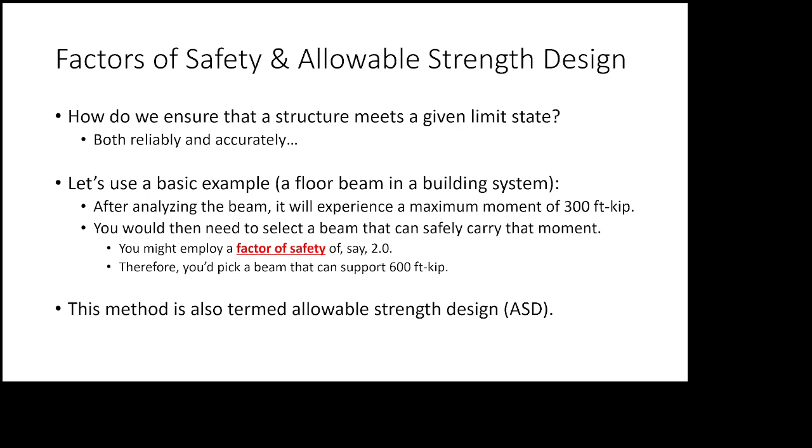For example, those of you that have had reinforced concrete design, probably when you did deflection assessment, you know that there is a difference between immediate deflections and deflections in the long term, right? And you have to compute effective moments of inertia. Over time, the reinforced concrete beam will crack more. It changes the moment of inertia, you get increased deflections. But then there are also material-related phenomena like creep and what have you, that the behavior of the concrete changes over time, right? That is a time-dependent phenomenon that we must account for, okay?